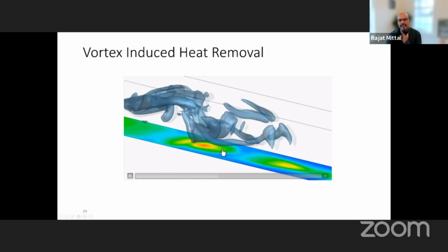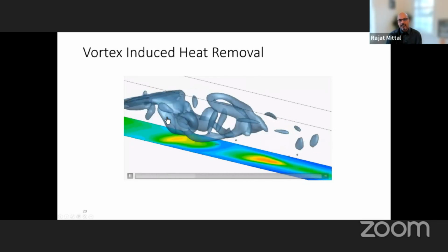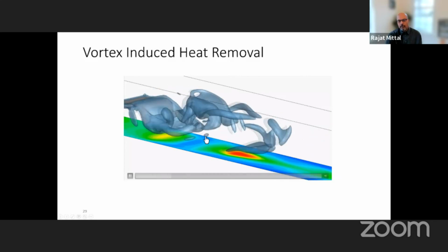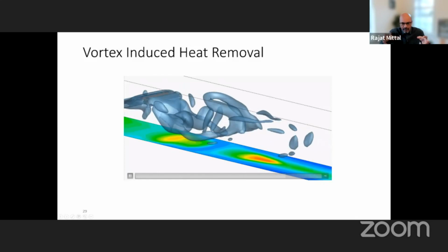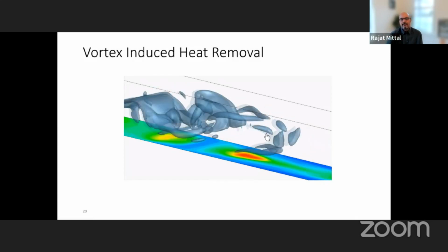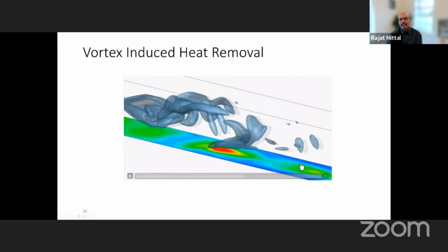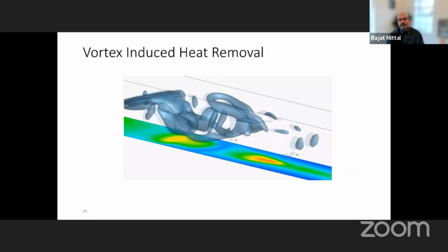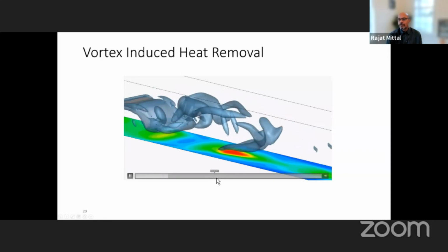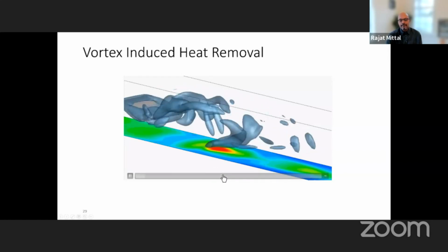And you can see that there's a lot of heat flux in certain regions. So it turns out that these horseshoe vortex structures that are formed are what basically drive the heat away from the wall and increase the heat transfer. So the basic mechanism of heat transfer in these 3D flows is the formation of these horseshoe-shaped vortex structures.